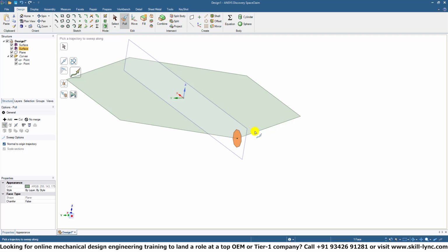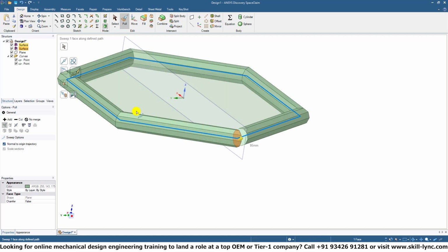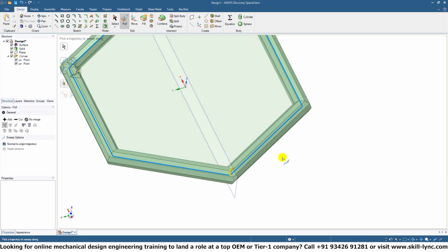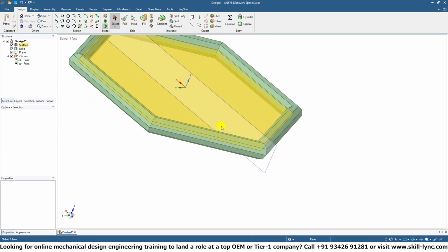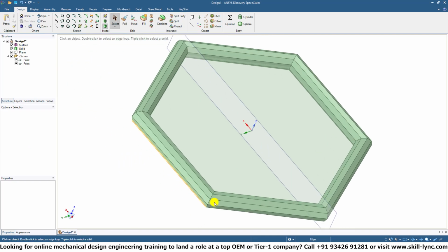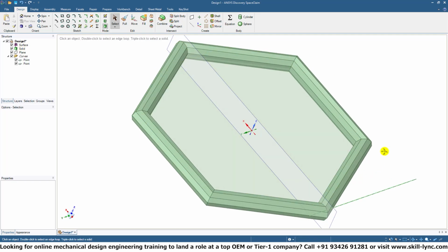Now we have to select the curve. Select here, here. Let's select all the edges of our original hexagon. And would you look at that? If we do the sweep pull, it will follow the edges of our original sketch, of our original polygon, sort of follow along and adjust the edges, extrapolate the edges over here into a joint and go along the curve itself. Right?